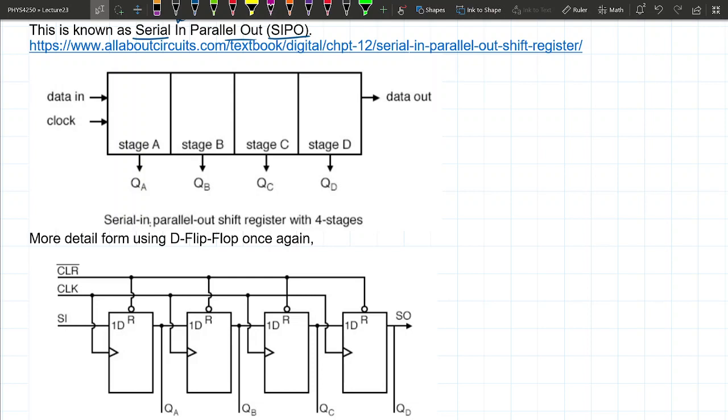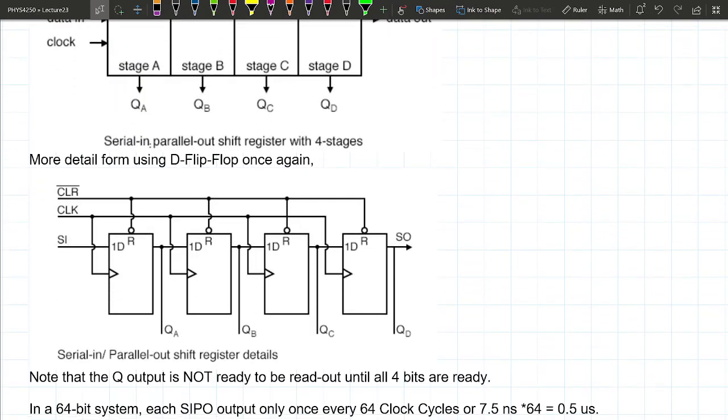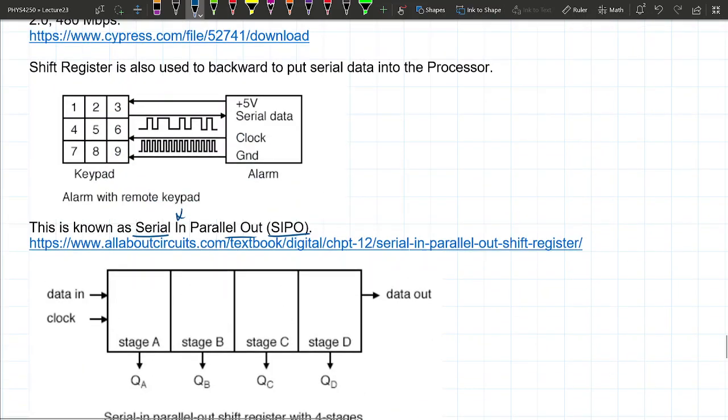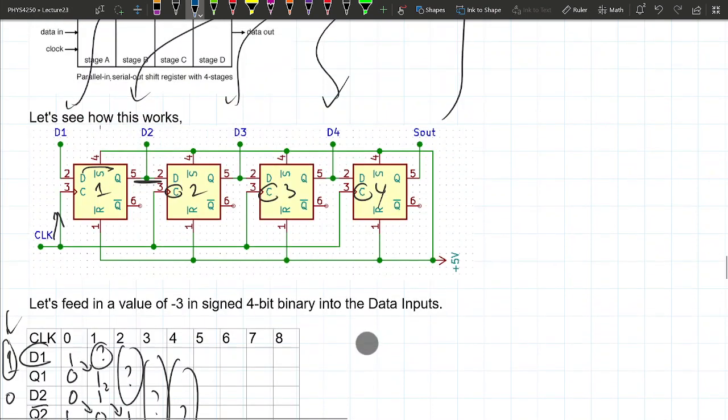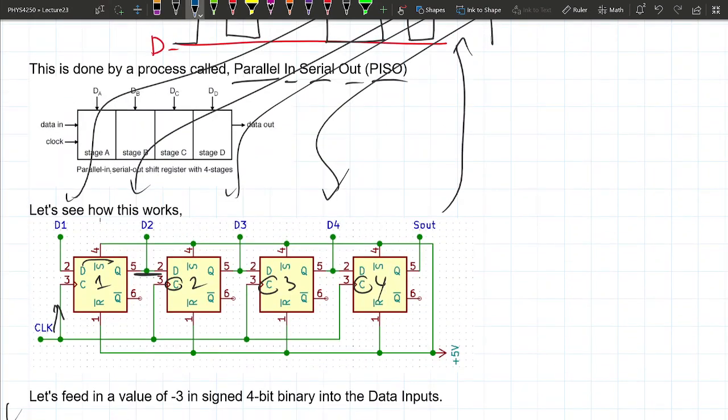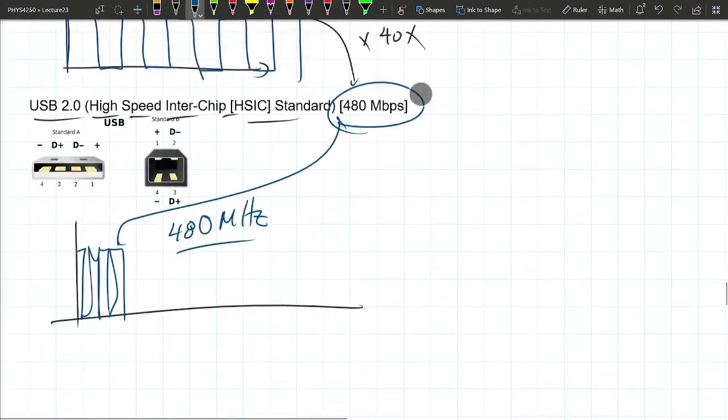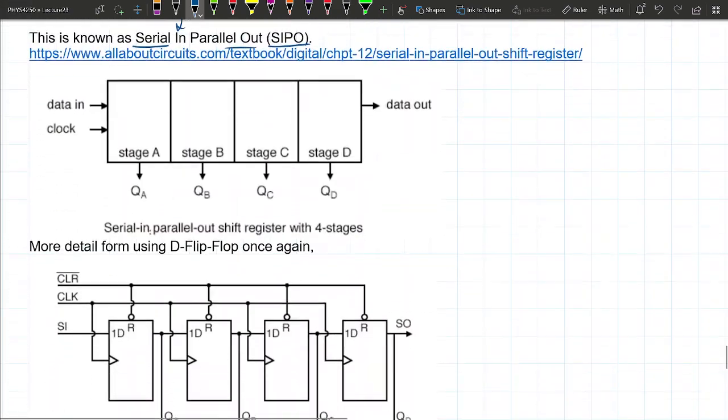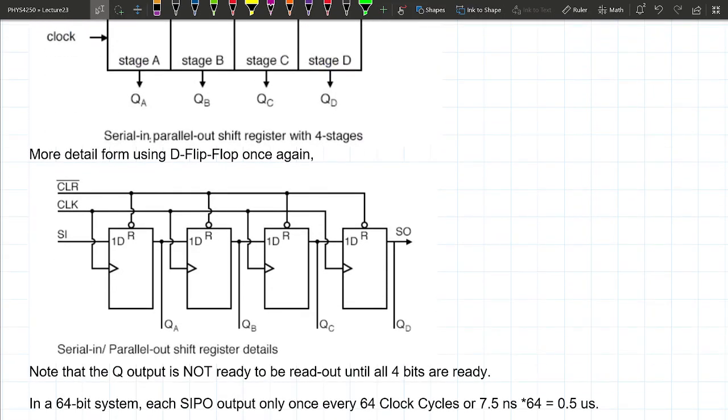compared to PISO. Similarly, let's go back up here. Unfortunately, it's kind of far away. The PISO circuit has these digital parallel inputs. Now, since we're going to go SIPO, serial in, parallel out, the input is just a single serial input, and your outputs are these parallel bits that you're going to write to your RAM or whatever you want to connect that to.